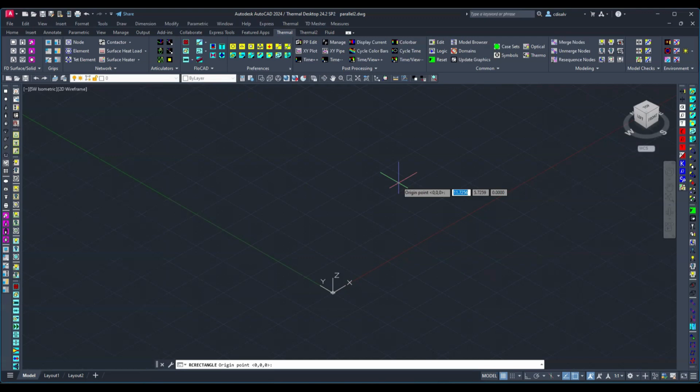You can enter either at the cursor where you can see it highlighted, or in the box at the bottom, the command line. So either way is going to work. So you can go ahead and type in 0 for X, hit a comma, goes to Y, hit 0 there. Okay, so now it is asking for the plus X axis, which is going to give us our length.